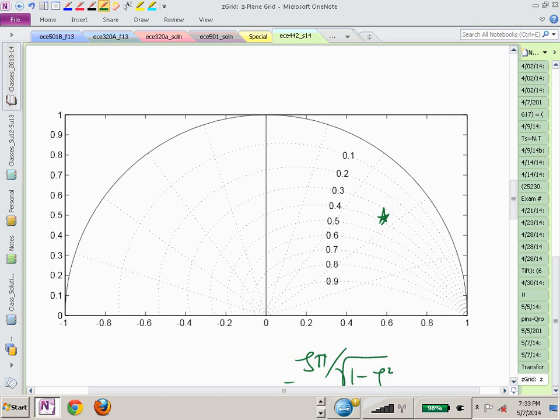And that might come from finding the closed loop transfer function. Maybe somebody gives you the controller and they give you the plant, and you put it all together in a closed loop system, compute the denominator, which gives you your closed loop dynamics, and you have one of your complex poles living right there. Maybe you had 6 different complex poles. How do you decide which ones you use?